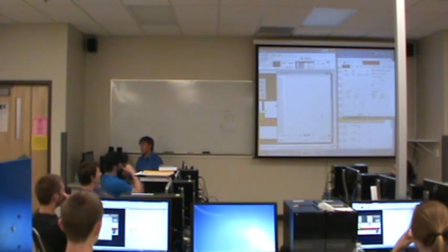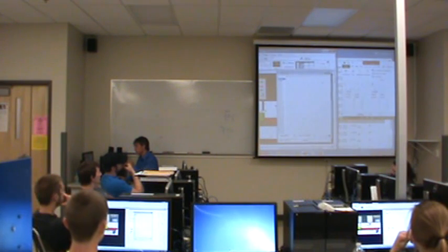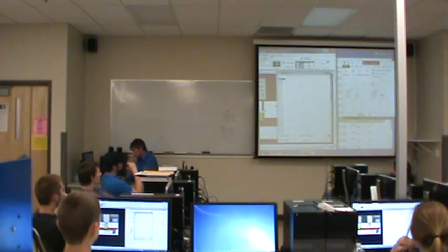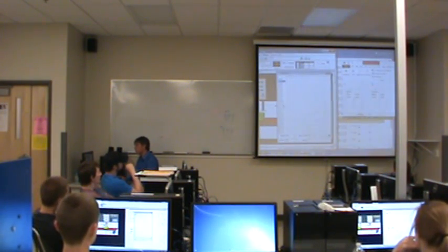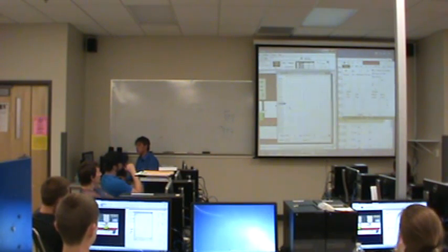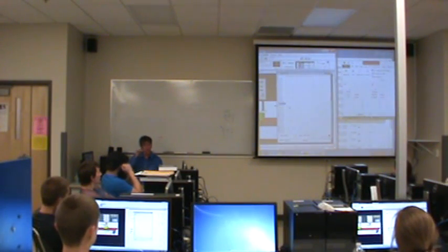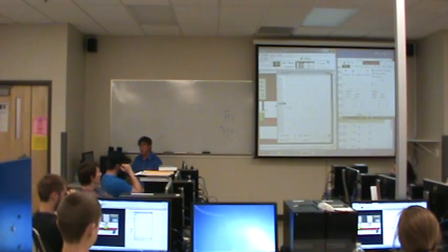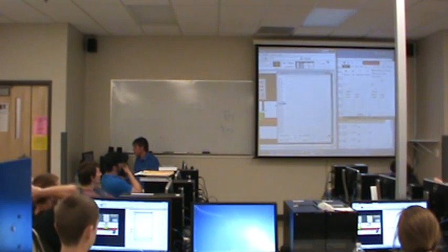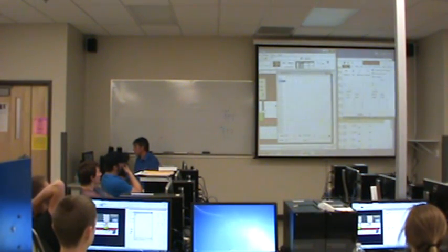Now, remember in my sequence instructions, I have the compare list, the inputs, begin at address 1, and the outputs begin at address 11. Because remember, I have to go 1 address past what I put into the command. Okay? So I'm going to put my input lists in here, starting at address 1.